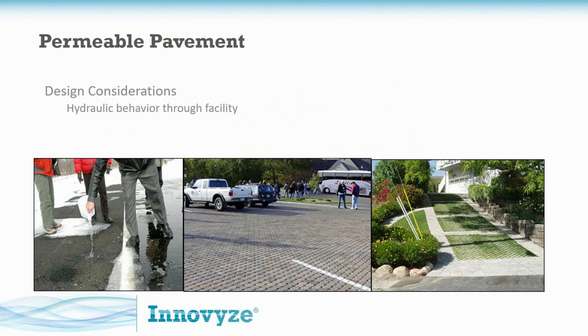Having the backup plan for if they get clogged, those kind of things need to be assessed. The important item here, site slopes. Well, in a parking lot, there's often some sort of even 2% grade to that parking area, even with pervious asphalt. So you can't just say, all right, this is a 2-foot deep structural fill with 40% void space. Here's my volume. No, you have to know that it's down a 2% slope. So your retention volume actually is much less. I mentioned this before, but account for the true layering of the structural fill and the flow through it. Really, really important.